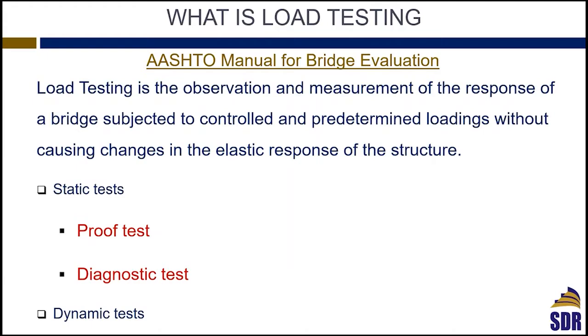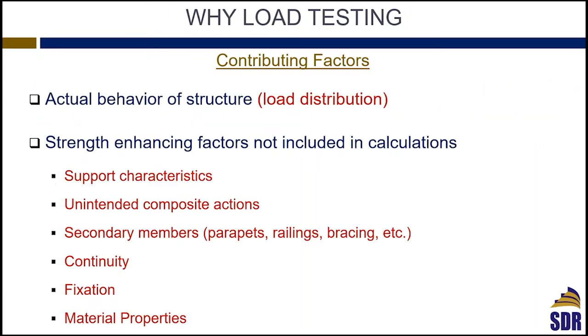So first of all, what is load testing? According to the AASHTO manual, in load testing we basically load a bridge with a predetermined load and then measure the response of the bridge under that controlled load. Generally, load testing can be static or dynamic. I would say most of the time we end up doing the static test. The dynamic is mainly done for other purposes, such as proof testing or diagnostic testing. Why load testing, or what is the benefit of doing it?